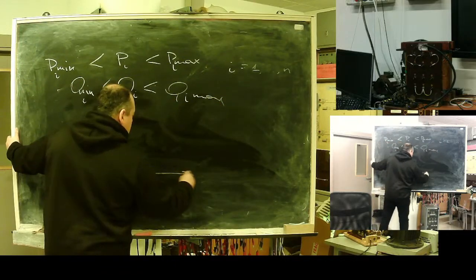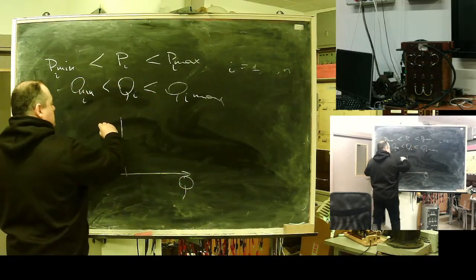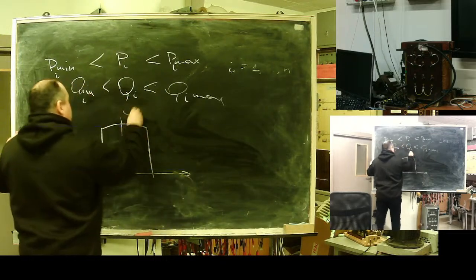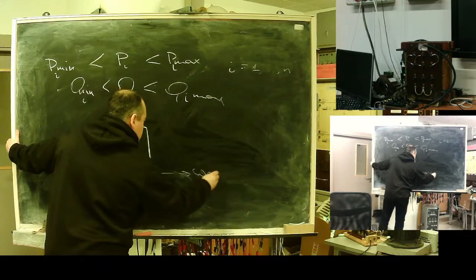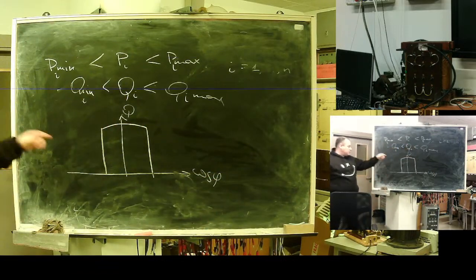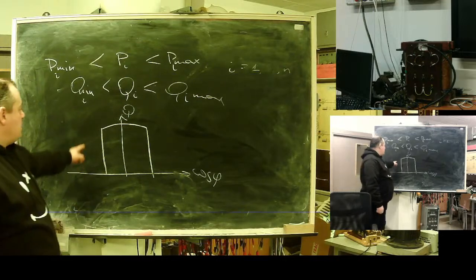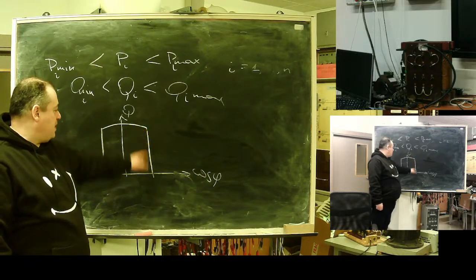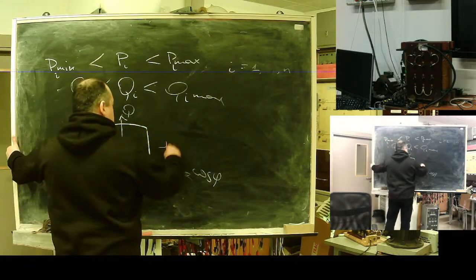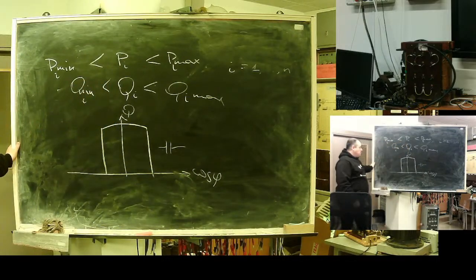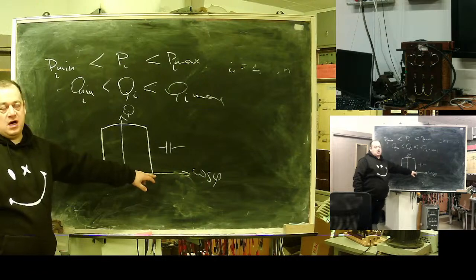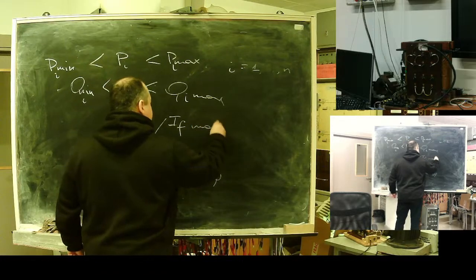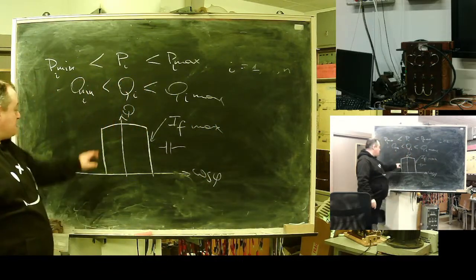You can see a chart like this. Here will be cosine. A chart like this is a limiting chart. This arc is set by the allowable generator current, the maximum. This is capacitance. This part is limited by rotor current, by excitation. And this part is limited by, I'm asking, you know it.